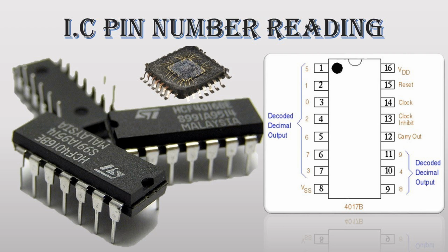Demultiplexers, DMUX. Function. Demultiplexers perform the reverse function of multiplexers. They take a single input and distribute it to one of several output lines based on control inputs. Output selection. DMUXs have multiple output lines and a set of select lines that determine which output line receives the input data. Applications.